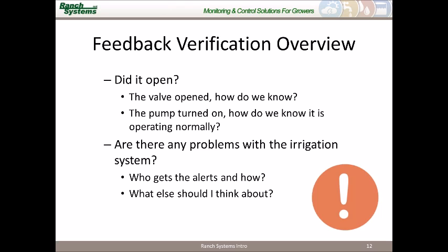So when you're building this, pressure relief valves are very important. Pressure sustaining valves or VFDs are a very good idea. But it's a good idea to discuss these with an irrigator or a planner so that you can have the proper shutdowns and mechanisms in the field so that no damage can occur. And then we can provide the alerts for that.